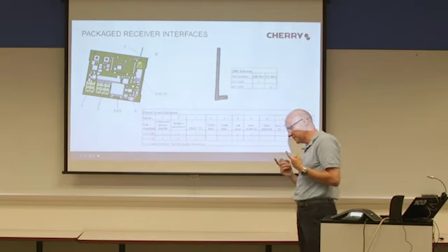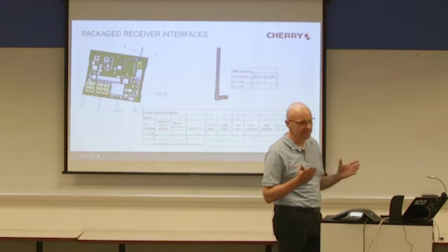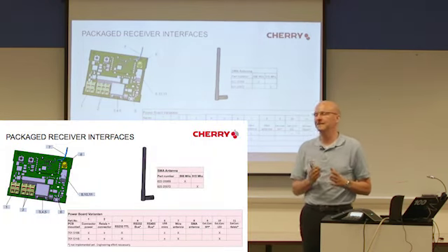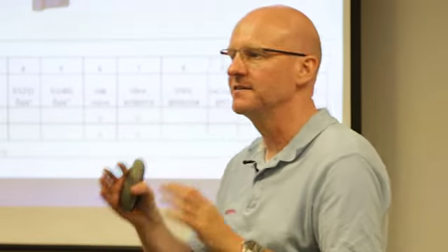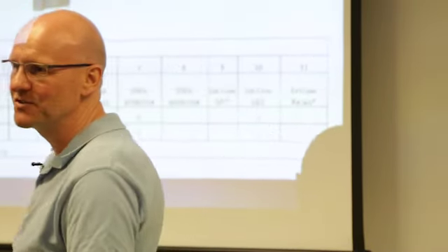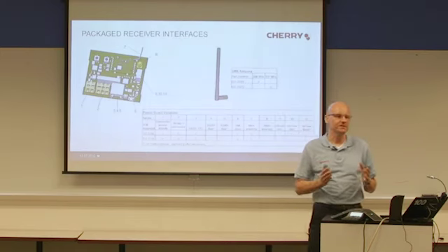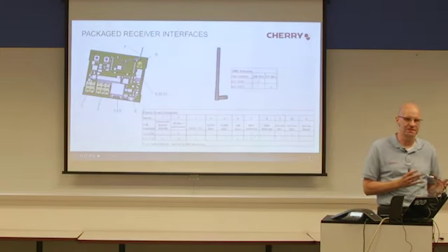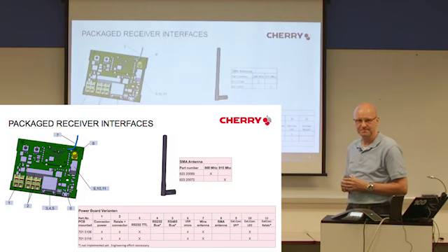So remember the structure of our RF protocol. In the RF protocol is described the language between the sender and the receiver. After the preamble, which is the introduction sequence, the knocking, and after the sync word, which says, hey, now the data starts, comes the real data which is necessary between sender and receiver. And the data consists of two parts. One part is the so-called unique ID, and the other part is the switch status.